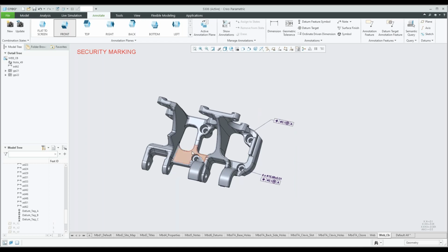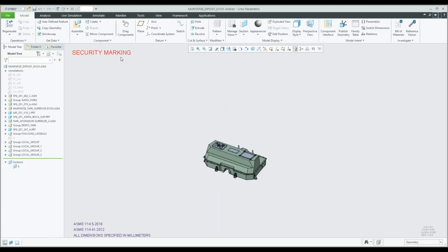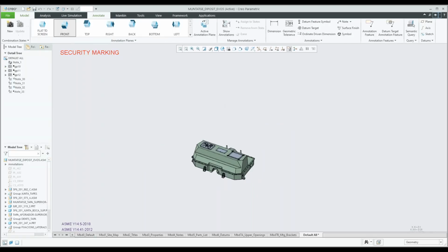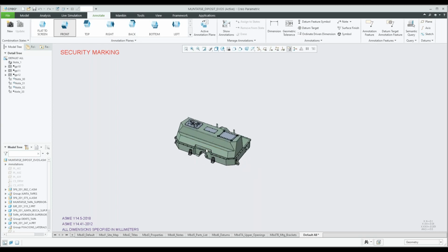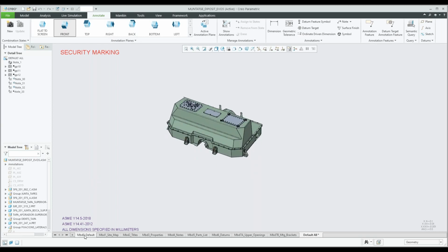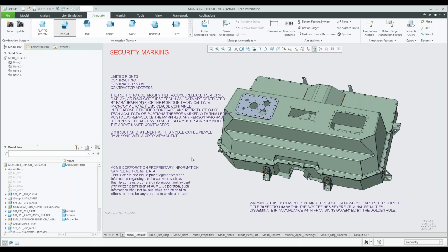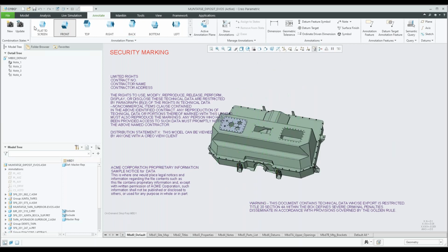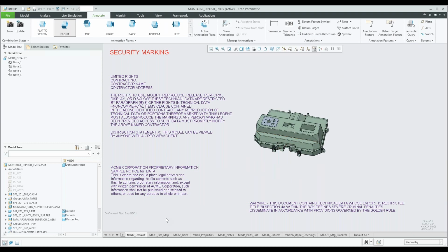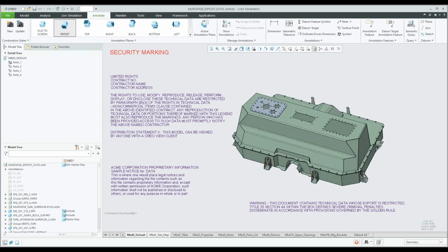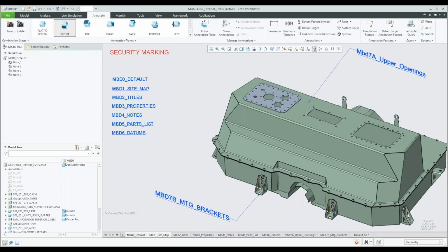For the assemblies, I'm just quickly going to open up one of the assemblies that I've done previously and just show you the interface, and the work method is exactly the same. So first thing, you have the same interface at the top. You're going to create it the same way. You need to specify your orientation planes, and then you can go and add your dimensions and tolerances and datum features. So let's just quickly scroll through this one. See what was added.